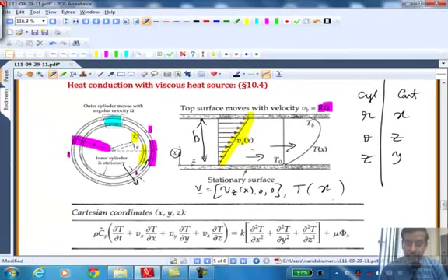Axisymmetry, right? That means whether I take in this plane or in this plane or in that plane, the velocity profile is the same. As I go around the axis, the center of the axis, it's the same. Okay, so in the Cartesian frame, you would call that a fully developed condition. There is no variation in the z direction. In the cylindrical one, you'll call it an axisymmetric case.